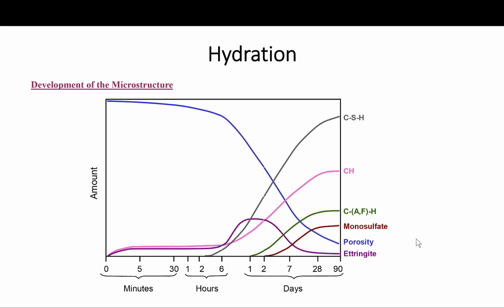Now, depending on the particle size distribution of the anhydrous cement and the degree of hydration, some unhydrated clinker grains may be found in the microstructure of the hydrated cement paste, even long after hydration. As stated earlier, if you remember, the clinker particles in modern cements generally conform to the size range of from 1 to 50 micrometers. With the progress of the hydration process, the smaller particles dissolve first and disappear from the system. Then the larger particles become smaller.